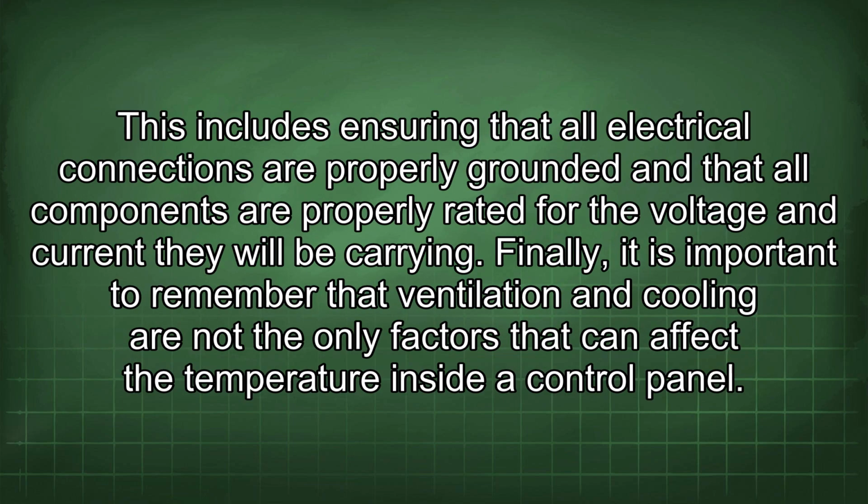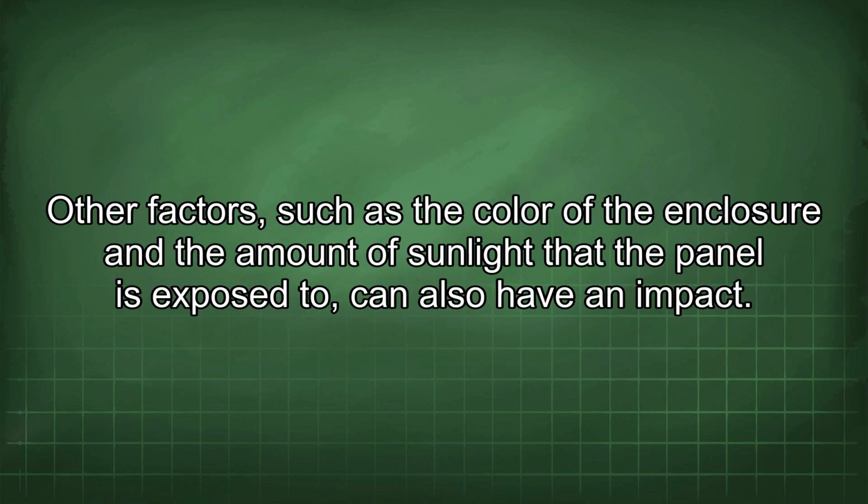This includes ensuring that all electrical connections are properly grounded and that all components are properly rated for the voltage and current they will be carrying. Finally, it is important to remember that ventilation and cooling are not the only factors that can affect the temperature inside a control panel. Other factors, such as the color of the enclosure and the amount of sunlight that the panel is exposed to, can also have an impact.